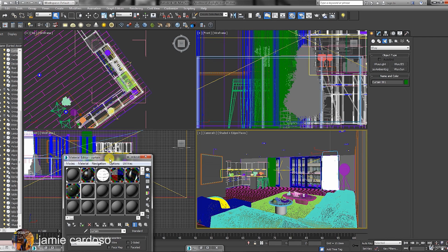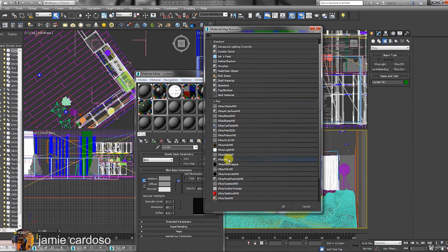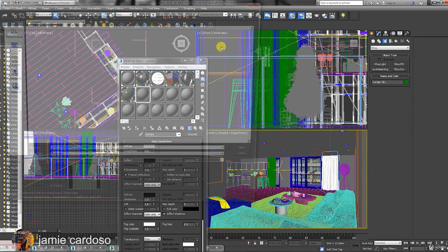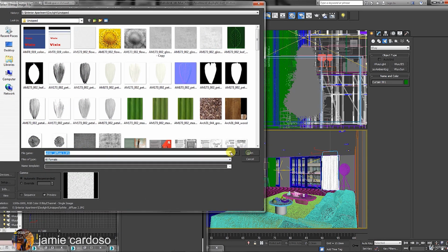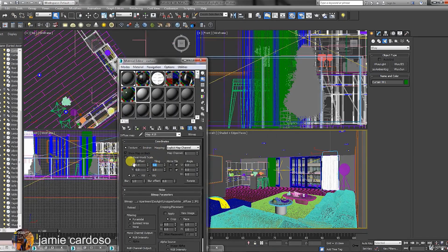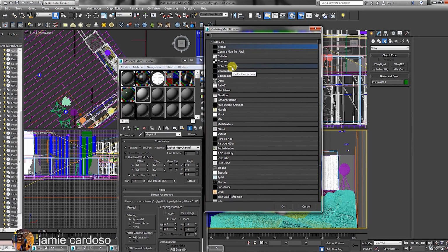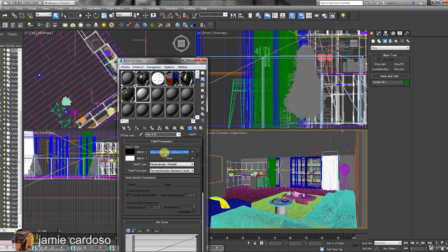The next step is to create the curtain material. Name the new material as curtain and load up the V-Ray material as previously done. Use the previous steps to choose the bitmap named white_diffuse2.jpg. Now that the texture is loaded, let's set the U and V tile to 8.0. Again, we're going to use a fall-off procedural map and the color correction to emulate the real surface.